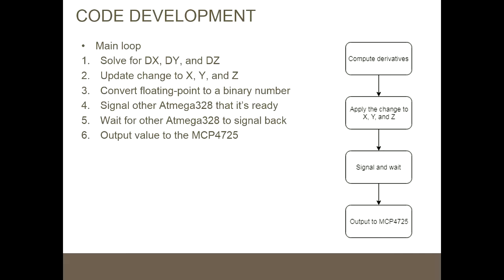The problem with that is that if the numbers are big enough, you're going to be doing a lot of iterations. And for the ATmega328, it's going to use up a lot of its clock cycles for this particular operation, slowing it down too much. It's absolutely inefficient. So what I did was implement the Booth multiplication algorithm,